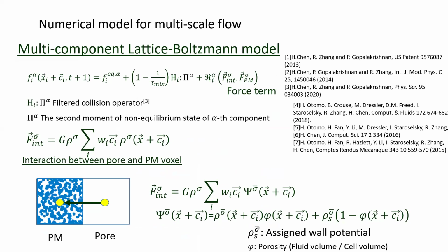One of the benefits of using lattice Boltzmann is that the pseudopotential form handles the wettability in the unresolved region. We naturally extend this pseudopotential form with the ratio of the porosity, the local porosity here. Then we can take into account the solid wettability from the unresolved region. More detail about the model can be seen here.